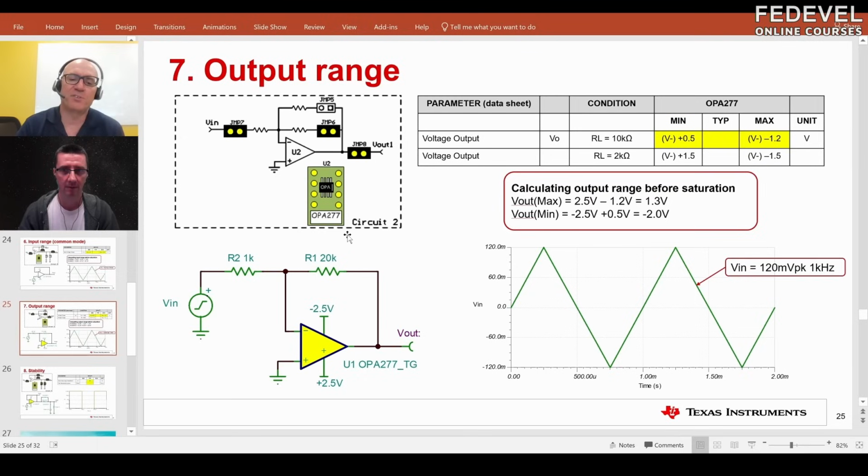One thing you do have to be a little careful of, let's say that this op amp was driving an A to D converter, and the A to D converter has an absolute maximum input range of 5 volts, meaning if you exceed 5 volts, then you could damage the device. If we put a 10 volt supply on the op amp, the op amp might be able to drive the 10 volts and could potentially damage the next stage.